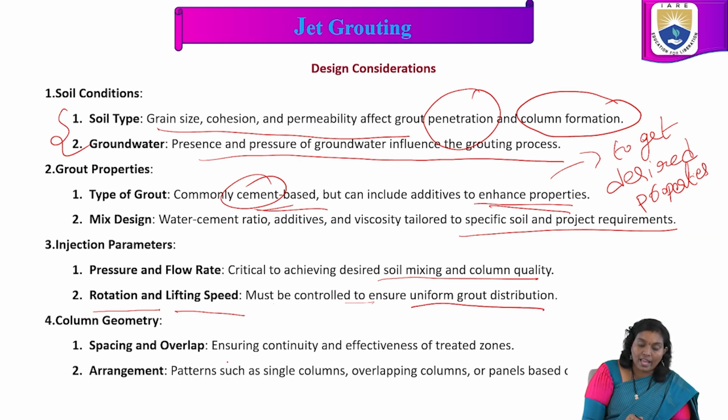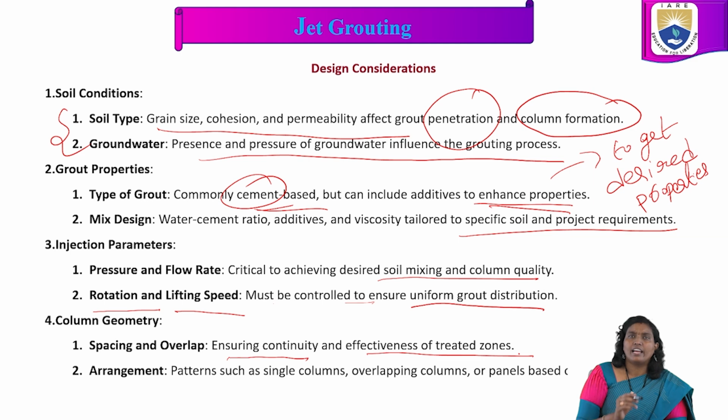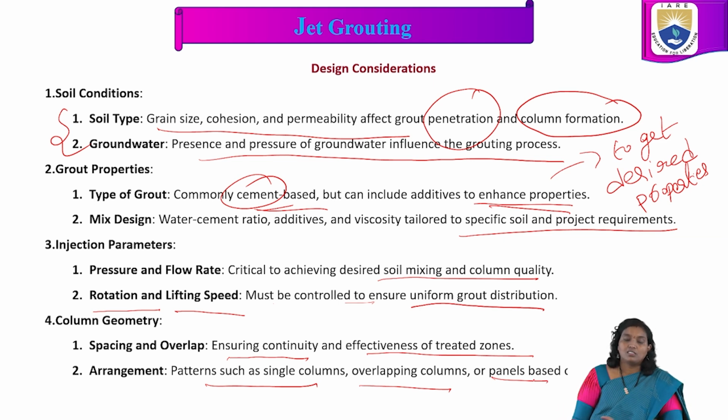Spacing and overlap ensuring continuity and effectiveness of the treated zones. Move on to the arrangements. Patterns such as single columns, overlapping columns or panels based on the project needs. So, these are the design considerations for jet grouting.